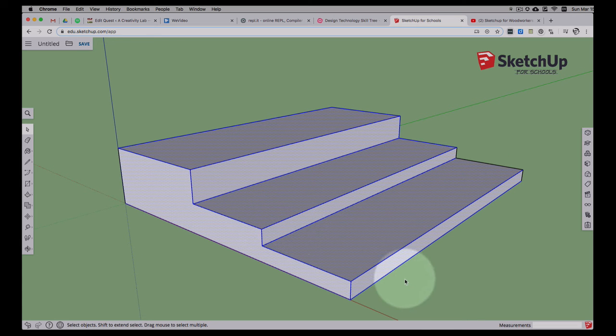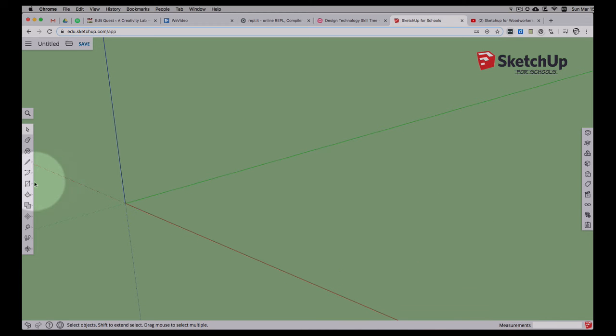But those are the 2 different selection styles. Up from the lower right gives you everything that it touches. Down from the upper left gives you everything that's totally enclosed. So in this case, I want to get rid of the entire staircase. So there we go. Now, let's go back and draw our rectangle.